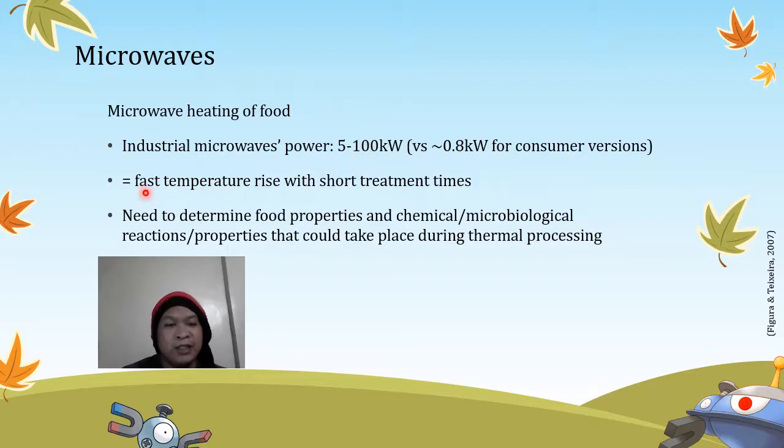Okay, and of course ang isa maganda doon is it could heat up the product in a very short amount of time because you're not relying on the limitations of thermal conductivity or the convective heat transfer coefficient for that matter, no? So of course these are more effective for smaller sizes of food products, and we want of course the products to have high absorption capacity of microwave radiation, so yung mga water-based products and those that are not likely to develop cold points are good options.